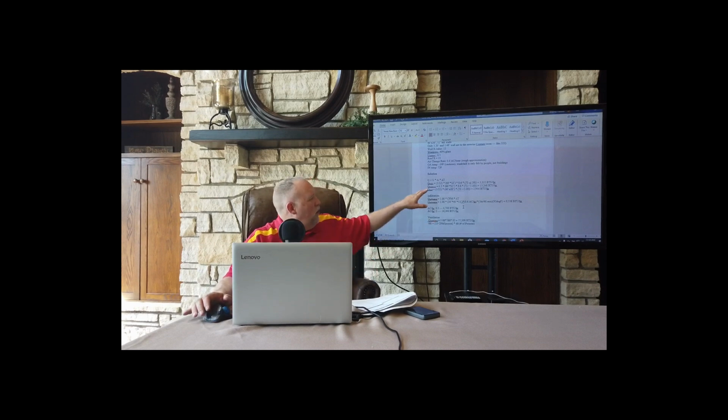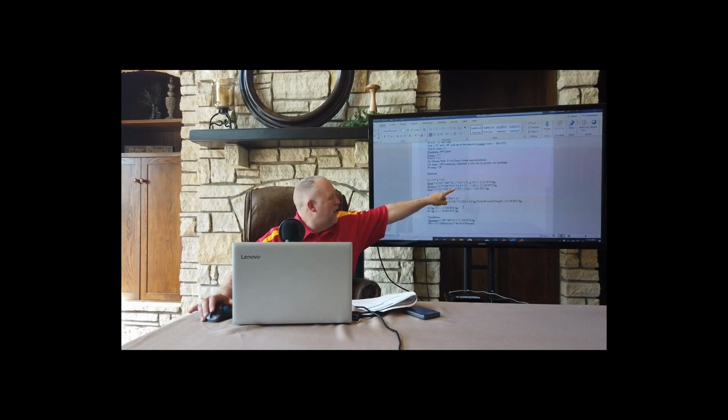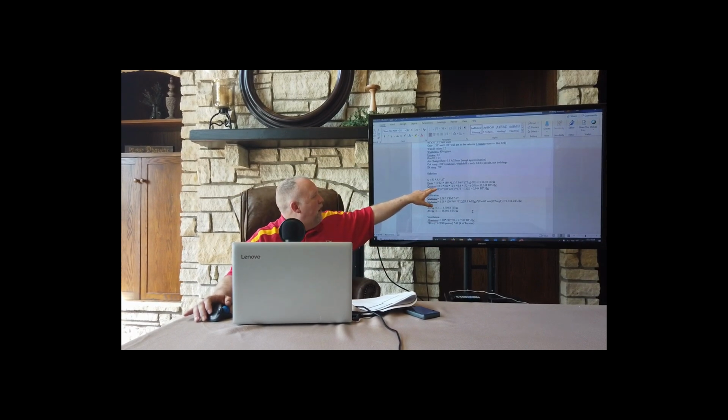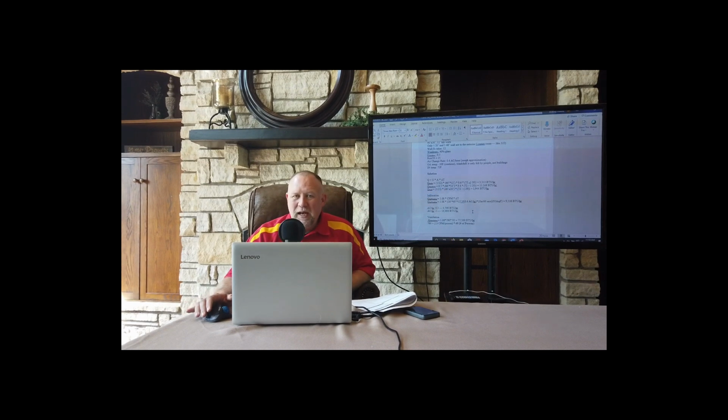All right, so Q for the windows, UA delta T, same equation, same area, but times 40% glass on that exterior. Same delta T, and we get 13,200 and some change. Q for the roof. We made the roof R value back up here. The roof R value is 25. The area of the roof in plan view is 40 by 20. We didn't mention anything about a skylight, so it's 100% roof and 0% glass, and we multiply that out.